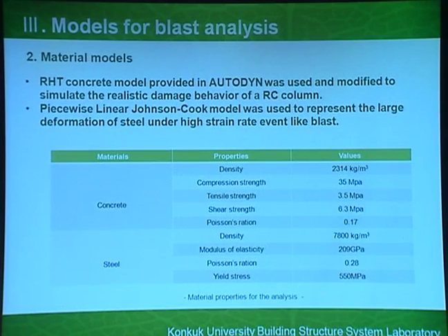Also, material modeling is required to simulate blast analysis. The material behavior is quite different from normal load, because of the very high strain rate. The strain change is very high, so the material model for this kind of analysis is quite different from a conventional material model. AutoDyn provides special material models for concrete and steel.